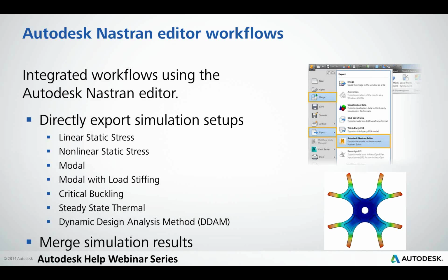So here, in the export workflow, you can export the setup of all those same analysis types, the first 6. So linear, nonlinear, modal with load stiffening, critical buckling, steady state. Plus, you can export a 7th analysis type, the dynamic design analysis method, which is basically the American naval shock testing analysis type.